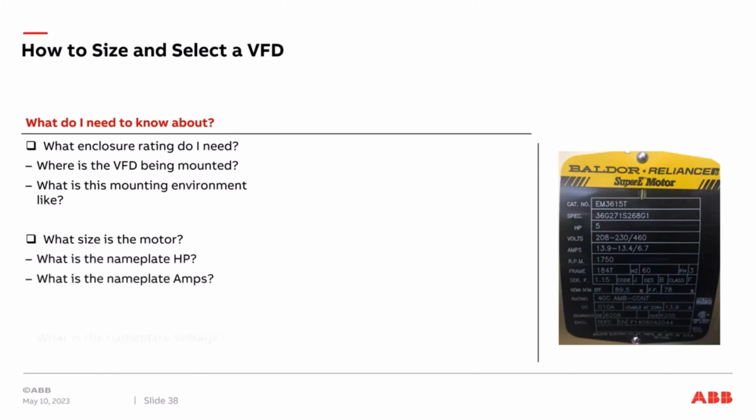What's the size of the motor? Look at the horsepower, the amps, and the voltage. Remember though, a VFD, when it comes to service factor, is a 1. On a motor's nameplate, you might see a service factor of 1.15. What does service factor mean?